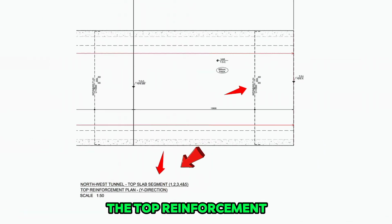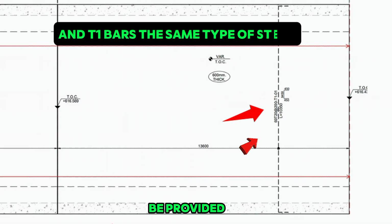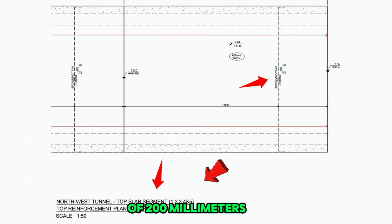The top reinforcement plan will have the same B1 and T1 bars. The same type of steel will be provided, and this will also be provided from one side to the other with a spacing of 200 millimeters.